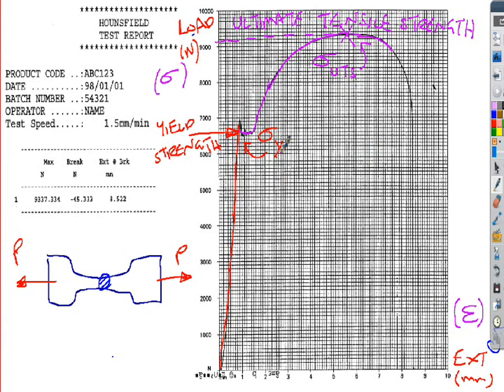Your maximum allowable stress and your factor of safety, which we looked at last week in the previous lecture, could be either of those, and that's given in the question. But I'm highlighting these because the first question we're going to look at talks about these two points on the stress-strain diagram. The gradient of this line, if I draw a right-angled triangle there, is the E value. That's the elastic modulus, or the Young's modulus value. So that's a tensile test, and those properties are particularly useful.